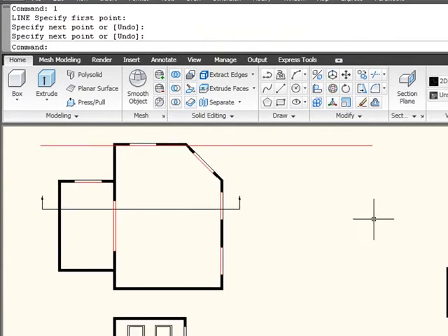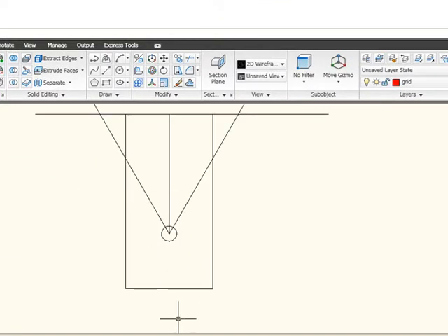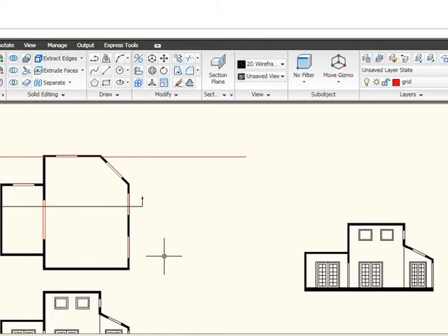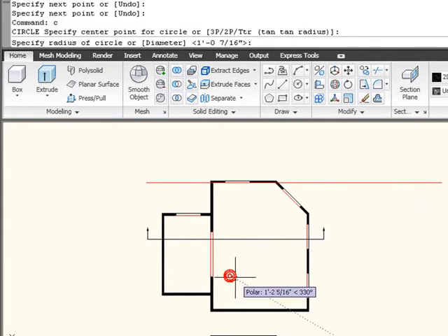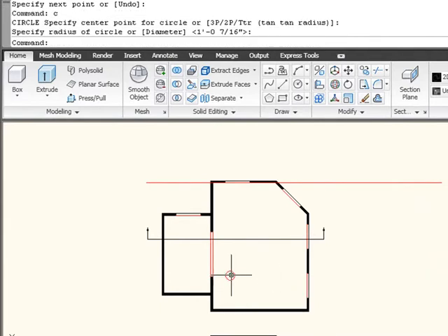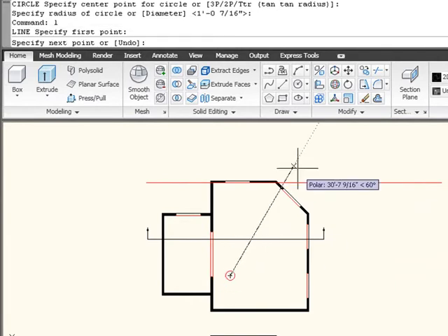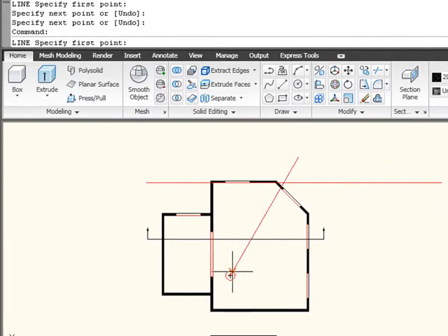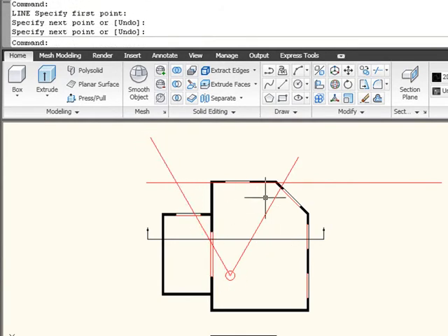The next thing I want to do is decide where I want to be in this space. In the first example, we put ourselves right in the middle of the room. In this example here, I want to put myself maybe, let's see, well, if we put a person here, then what we're going to see, let's go ahead and put our viewing plane in there, or cone of vision in there. There's the 30 degrees in that angle and the 30 degrees in this angle. Everything outside of that cone of vision will be distorted.